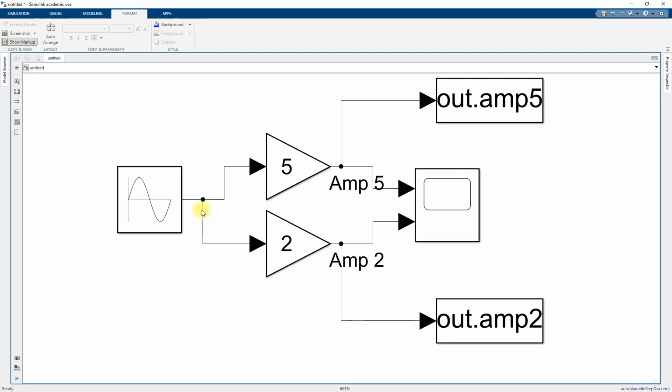So to review quickly, we talked about the Simulink environment, how you can create a new canvas, how you can add your Simulink blocks from the library browser from different categories depending on the needs, how you can change some of the feel and looks of these blocks, and how to export, look at the outputs, change the type of output you can look at, plot them, get the output in vector format, and also get the Simulink model in vector format.